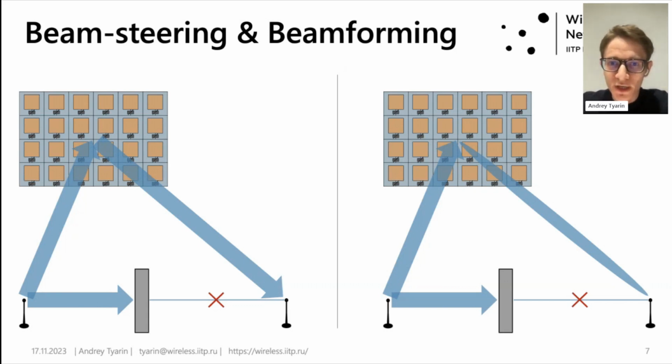Via beamforming, RIS reflects the power of the EM wave and focuses it in a certain point in space. To implement beamforming, it is necessary to create different phase shift differences between adjacent UCs, unlike beam steering. With the help of beamforming, one can amplify the signal from the transmitter on the receiver even more than beam steering.